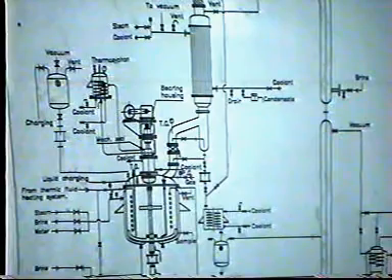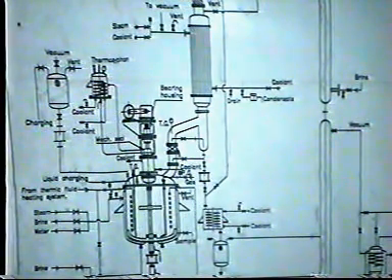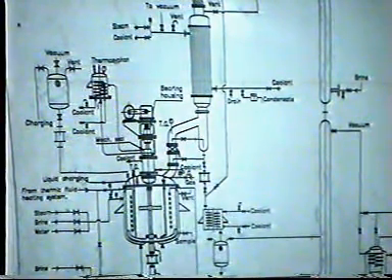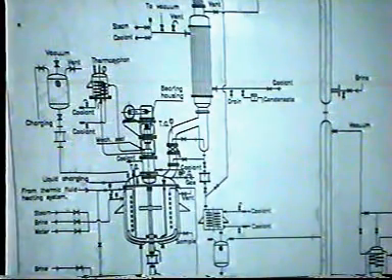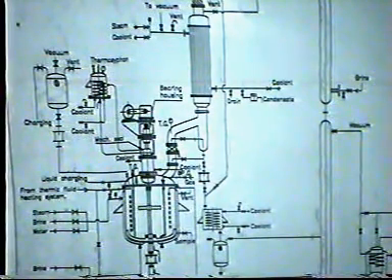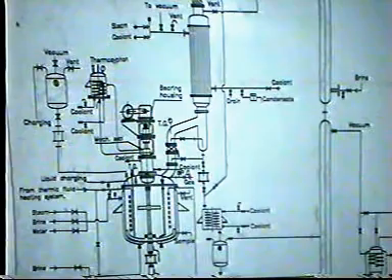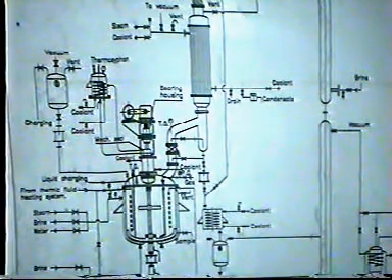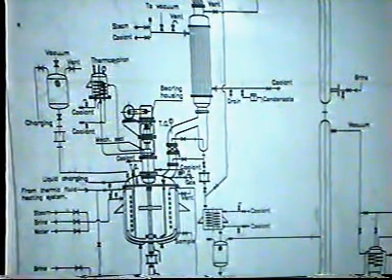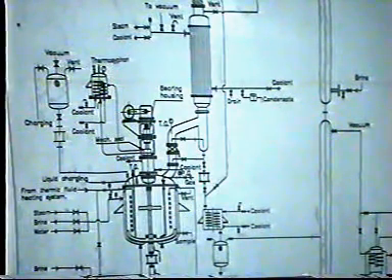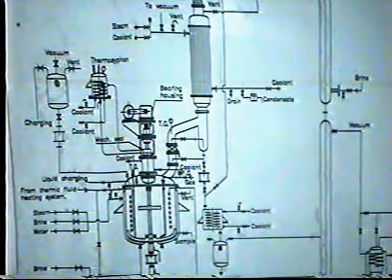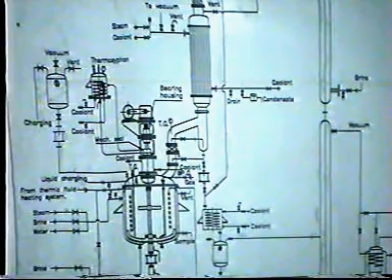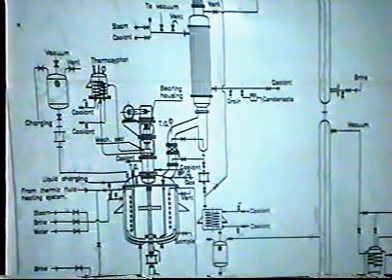A primary reflux condenser or a heat exchanger with a facility to heat or cool. On the top of that vapor head is a primary reflux condenser or a heat exchanger, as we may view it. And this is the one which is provided in between the column and the main reactor, because sometimes you would like to use this assembly as a short head, short distillation unit, and maybe sometimes just a reflux condenser.